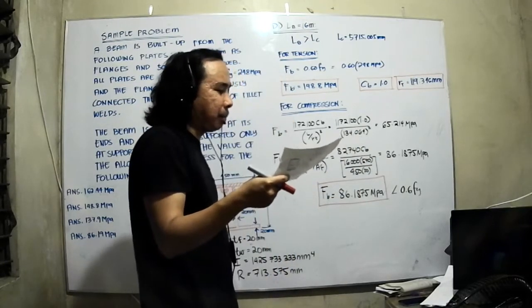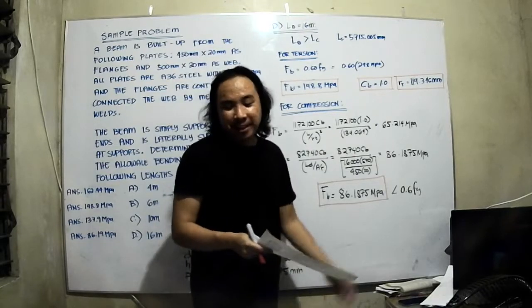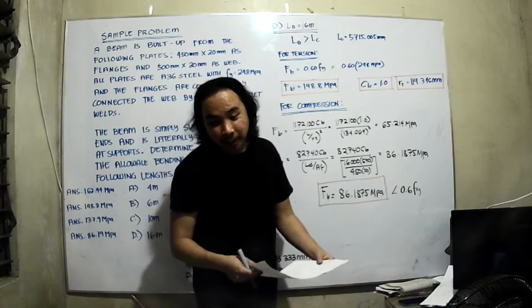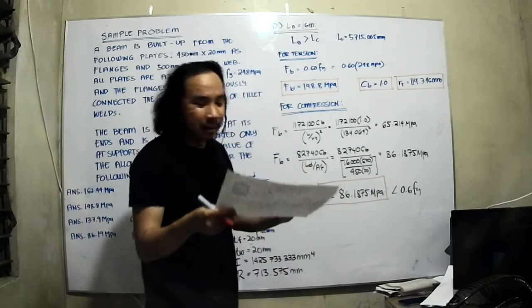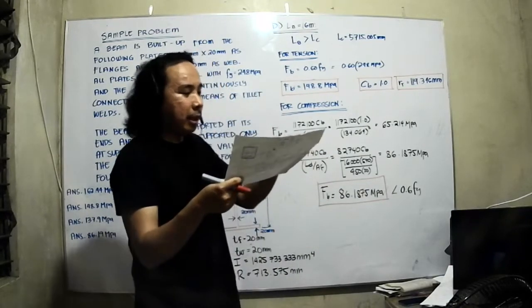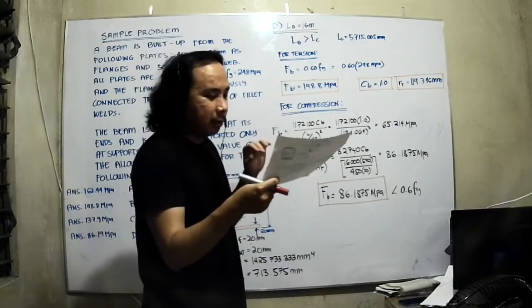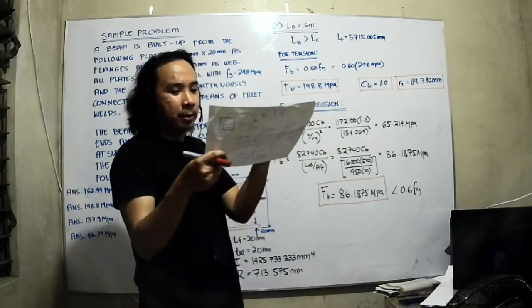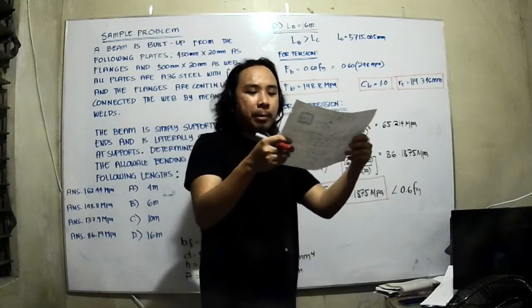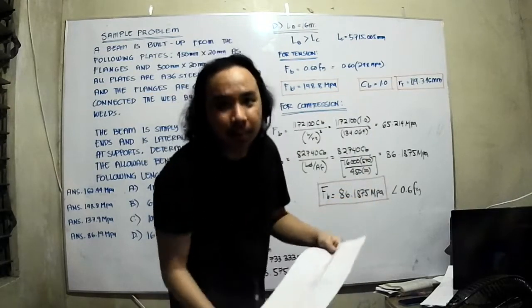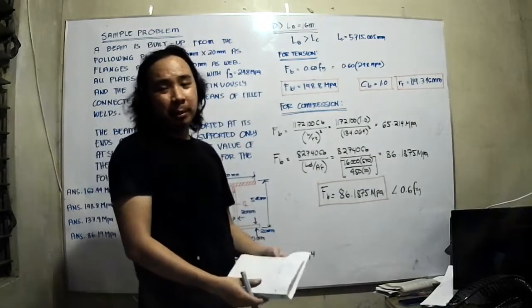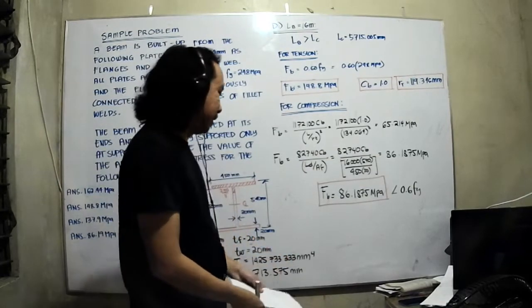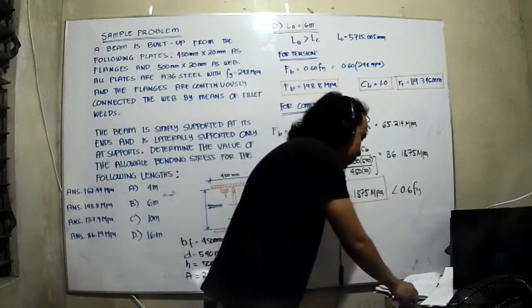We didn't solve a compact section, but for a compact section it's only 0.66 Fy, so it's very easy. We don't need to mind that. But here we have covered non-compact and non-slender sections. For built-up members, which are more complicated, we also went through them. So more or less we've covered all of that, right? I think we're okay with what we've covered.